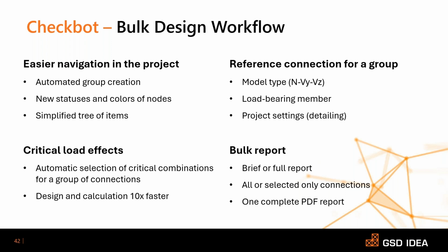Also, bulk operations are now possible in Checkbot. You can extract either the brief report or a full report of all the connections in the Checkbot or the selected connections. Just assume that if there are 200 connections, you have to open each connection, take the report for each IDEA StatiCa file, and merge them all together to form a document of 200 connections.